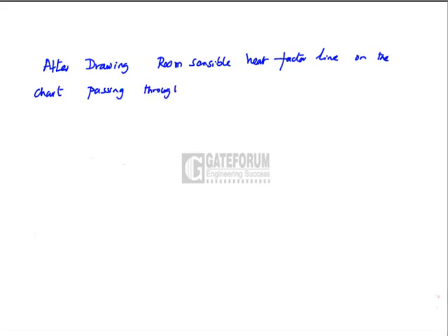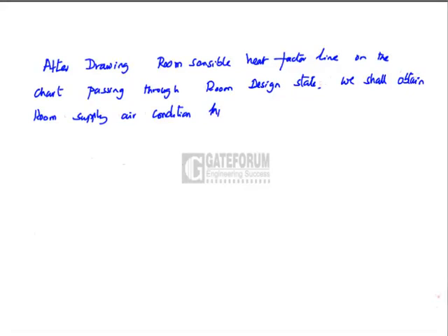After drawing the room sensible heat factor line on the chart, passing through the room design state, we shall obtain the room supply air condition H4.